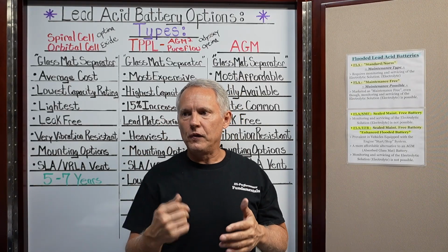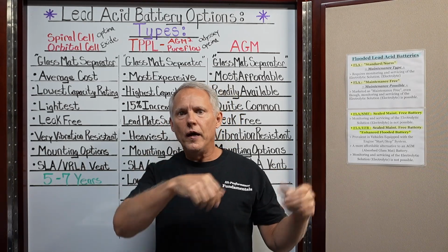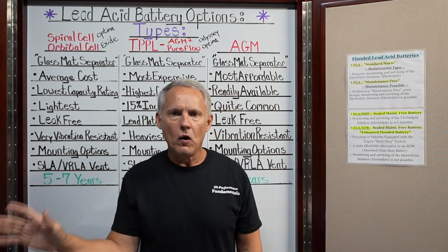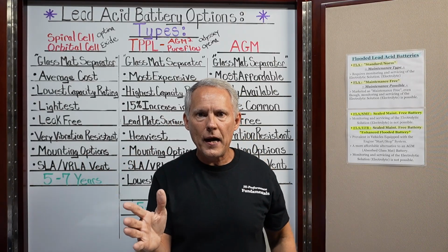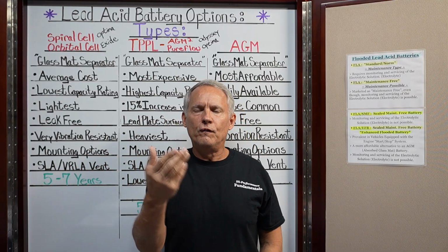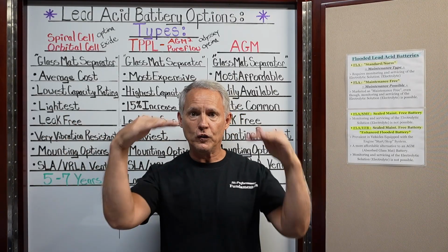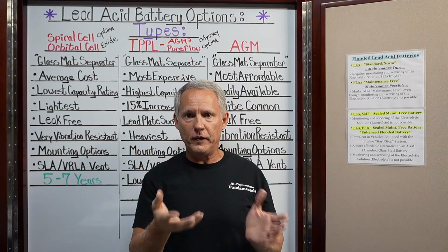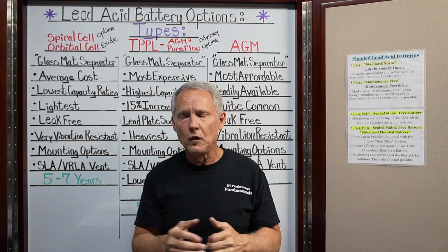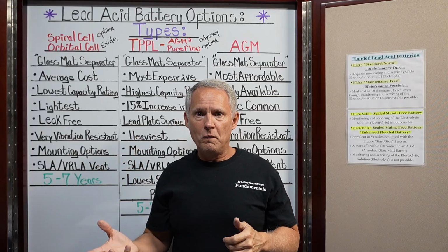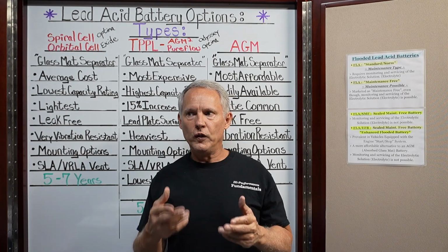So the downside to it is this: if you take a 12 volt battery out of a normal car or truck, and you drop in a 14 volt battery, the alternator or generator on the vehicle is not designed to charge a 14 volt battery. As an example, after the car is not running and the battery has sat and the voltage has stabilized, a fully charged 12 volt battery is going to be about 12.6 to 12.8 volts. A 14 volt battery is going to be about 14.7 to 14.9 fully charged.